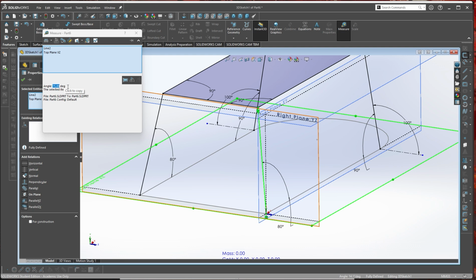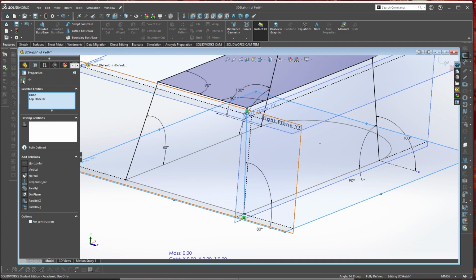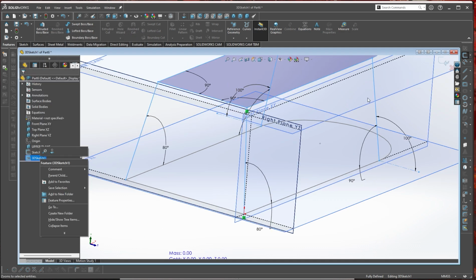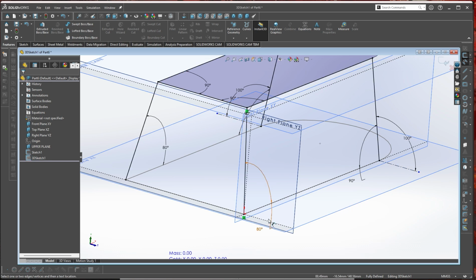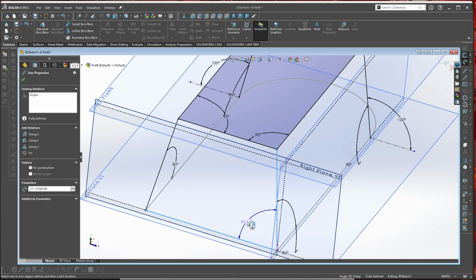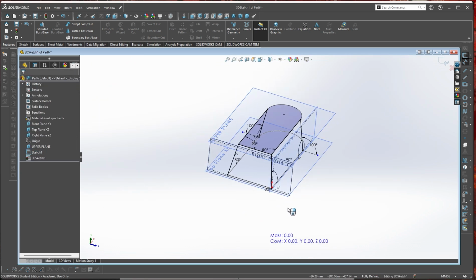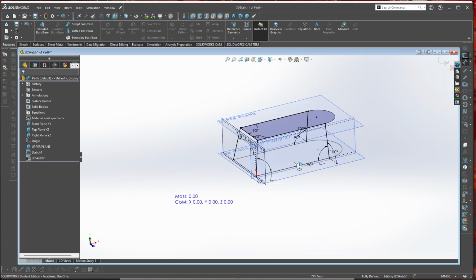Notice the angle, 75.89. So in other words, something is not quite right when it comes to measuring from this to that angle right there, in either direction. If I click here, edit the sketch itself. Oh, I'm already editing a sketch. Let's measure from here to here. You notice the number, 80.15. So, in other words, there are some inconsistencies depending on how we want to go about doing this.